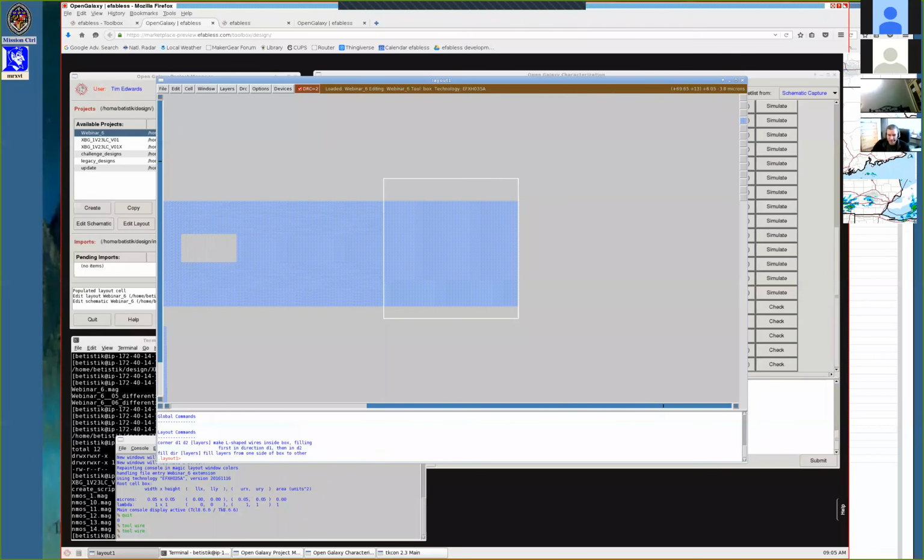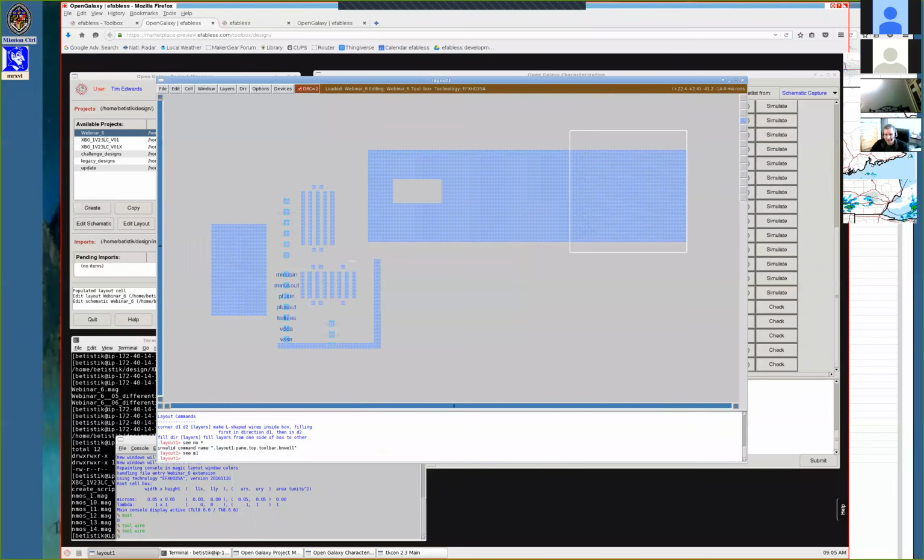Right, although there's also a command there, which is see no star, and then you can go see metal 1, which is probably more appropriate in this case because that gets rid of everything. Since the diffusion layers are not listed over here, then you can't. Yes, got it.